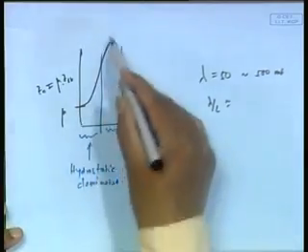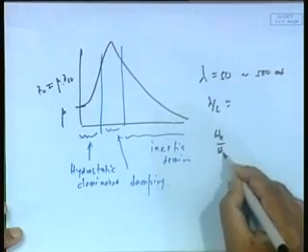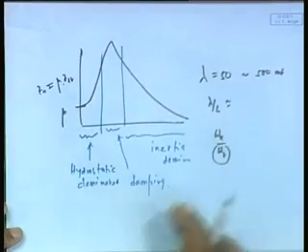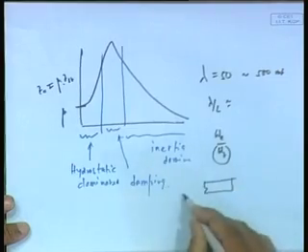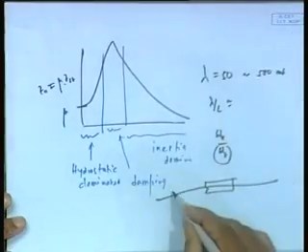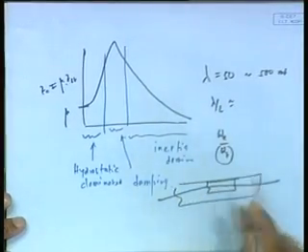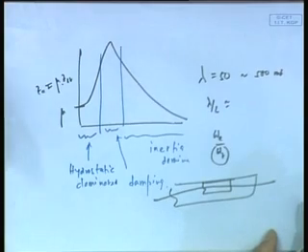Because again this response will depend on, remember, omega E by omega Z. So omega Z comes into the picture, omega Z of course will become low, this I will come to later on, but let us say that if the ship is this, and if the waves are much longer with respect to that, you expect it to go up and down. But if the ship is much longer with respect to this, then obviously you have a situation where you have essentially a relatively high frequency wave.